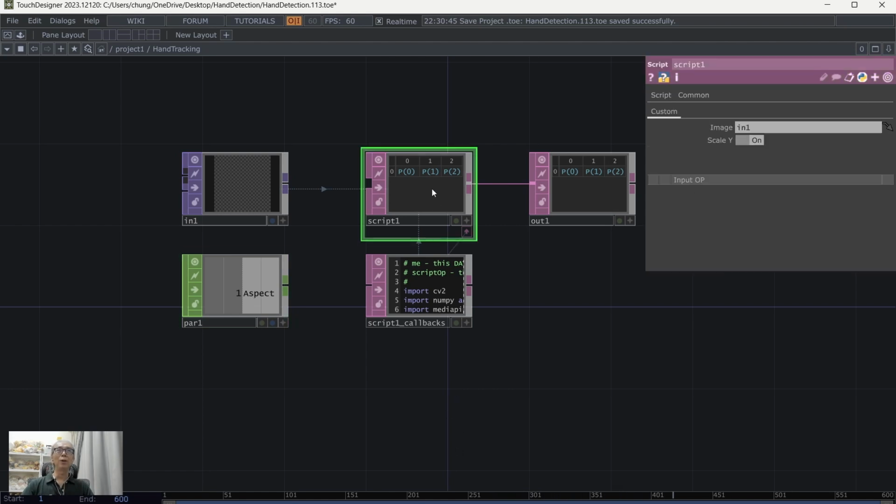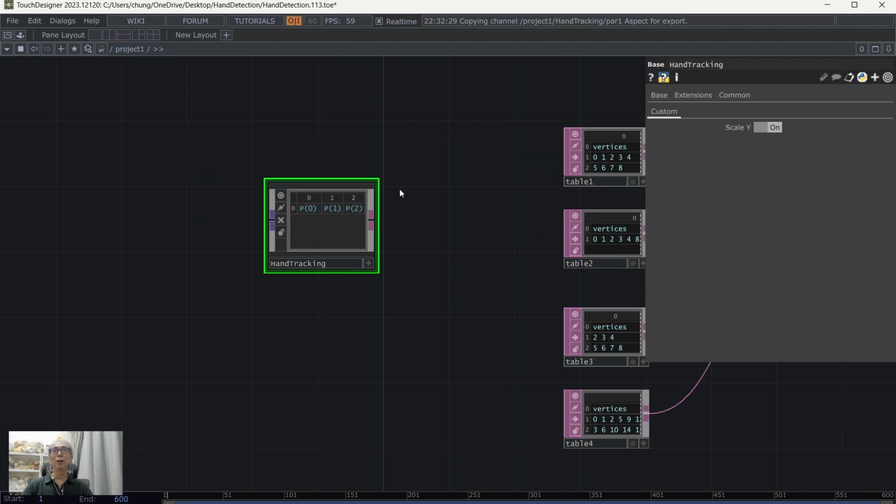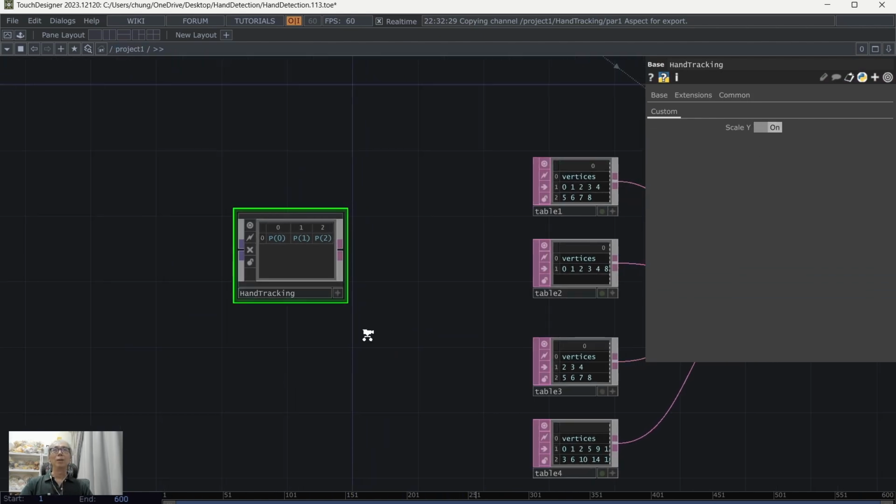With this one, we can connect them using the traditional TouchDesigner export CHOP option. So we can just turn on the viewer active, drag this one to the button, and then release your mouse to export CHOP. So now this one is connected here and also connected back to this particular toggle button.